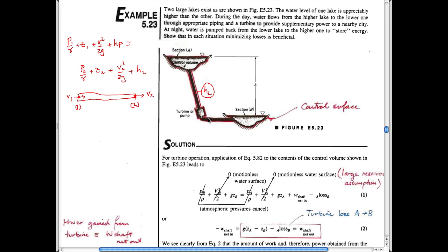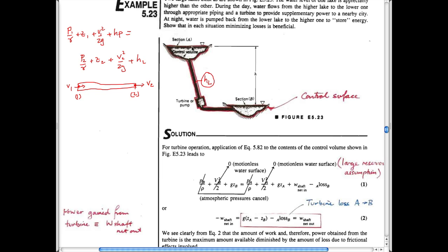Well, it's sort of self-evident, but let's go through it anyway. So you can write the expression that we have here in terms of flow if you're producing power through this. So if you're running this as a turbine, then what are these? This is written in terms of, yeah, it's written backwards. So this is the upstream part. So this is upstream pressure, upstream velocity, upstream elevation, the shaft work that's in the system. We've normally written it in terms of then the downstream pressure, the downstream velocity, the downstream elevation, plus head loss, right? So this term here is merely on this side because it's there. It would normally be on this side. So this is the upstream portion, this is the downstream portion.